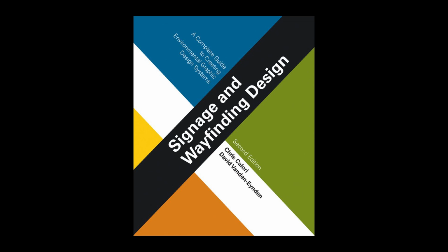Sign paints typically require a primer or base coat that's applied directly to the sign material before application of the top coat, which contains the selected color. Sign paints are usually applied by spray gun to achieve a smooth, even surface, and are baked in a large oven after application to cure the paint, which dries and hardens it. In addition to opaque sign paints, there are also liquid clear coatings, which typically perform a protective function while allowing the base material to show through, just as clear polyurethane varnish protects a wood floor while allowing the beauty of the wood's grain to show.